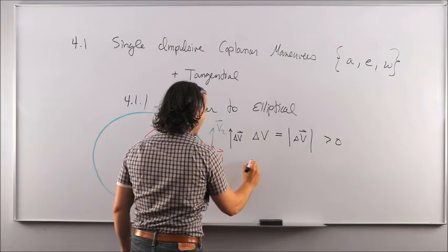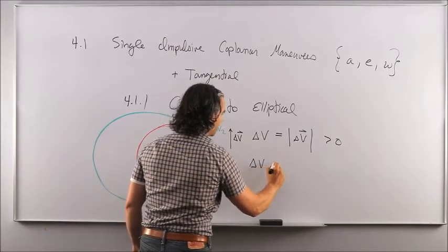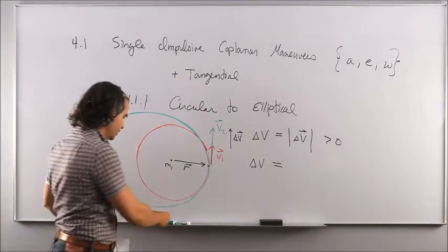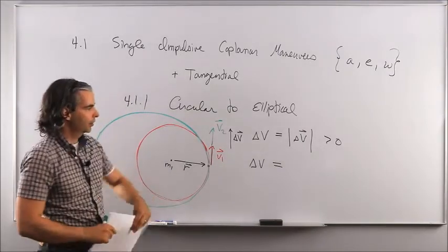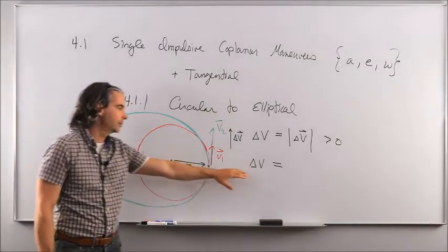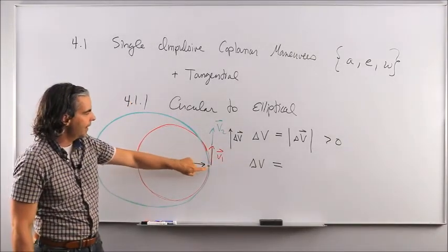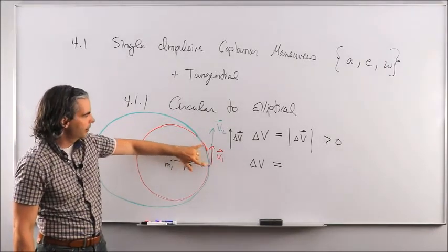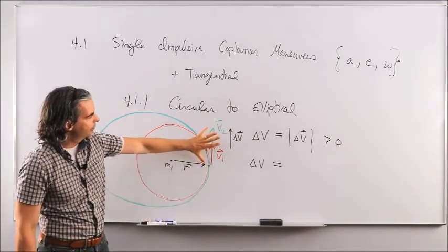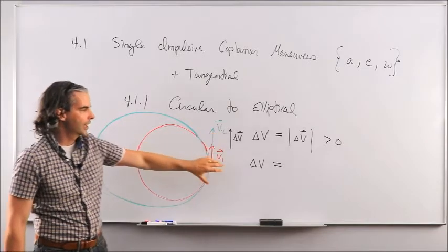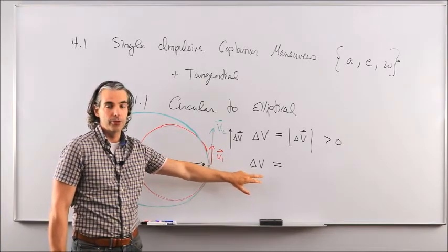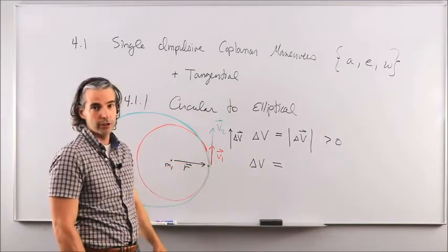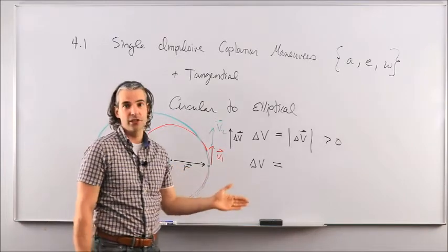So when we're going to look at delta V in terms of scalar, then we have to make sure that we do the subtraction in a proper order. Because if you want to calculate delta V and you were to take the speed that the spacecraft had at this point along the red orbit, which is V1, minus V2, then you would obviously get a negative delta V, and I would remove 50% of the final mark for that question, because delta V negative is just impossible.